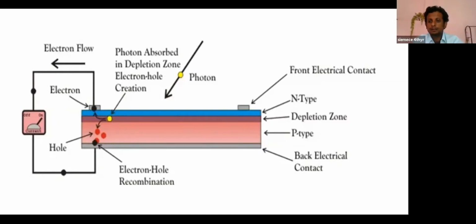Then we apply a few thin electrodes on top of the P-type semiconductor layer. These electrodes do not obstruct the light from reaching the thin P-type layer. Just below the P-type layer, there is a PN junction. As we are all electronics engineers, we know what a PN junction is very clearly; we studied it previously in solid state devices, so it will be much easier. This is the basic construction of a solar cell.